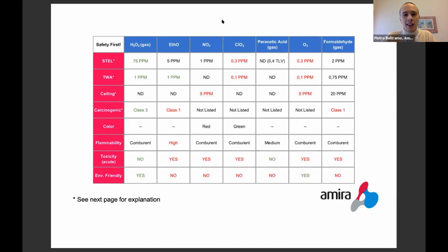It's a chemical reaction, and that could be an expected result. For example, a couple of years ago, I did a study for a company manufacturing anodized aluminum, so aluminum with a color coating. They were working in the pharma field, and they had a hard time finding the right coating, because it looks like most of the coatings on aluminum get discolored by the H2O2. It doesn't matter if you use the liquid or the gas. The H2O2 slowly takes the color out of the aluminum. Then you have a gray aluminum, no problem, you know. But if you want to sell a blue aluminum and then it comes back to gray, that's not good.